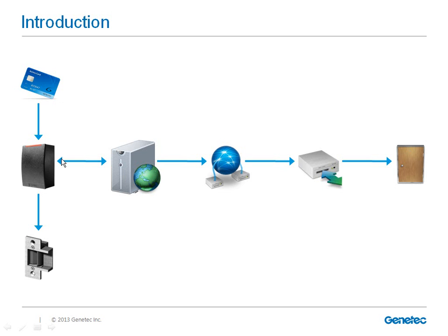Credentials are presented to the door reader, which in turn unlocks the physical locking device if they are valid and the person may be allowed to pass through the door. Now, we can have trouble spots at several places along the line. The first problem you might see is actually adding the unit to the access manager. This could be a problem with the unit, with the connection between the server and the unit, a problem on the access manager side, or with the unit entity details.